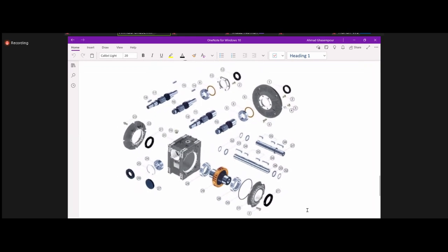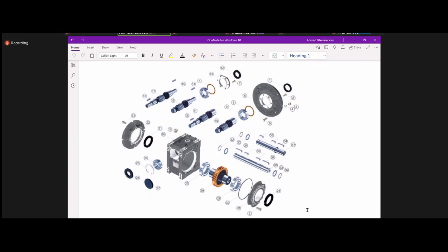This is an example. Obviously, there are things which are not manufactured by a gearbox manufacturer, like bearings, fasteners, keys, and so forth. So those you don't have to design. I think these days you can find solid models for almost all of them from the suppliers. What you have to do is basically flanges, shafts, housing, things of that nature. Right, so that's the first milestone.